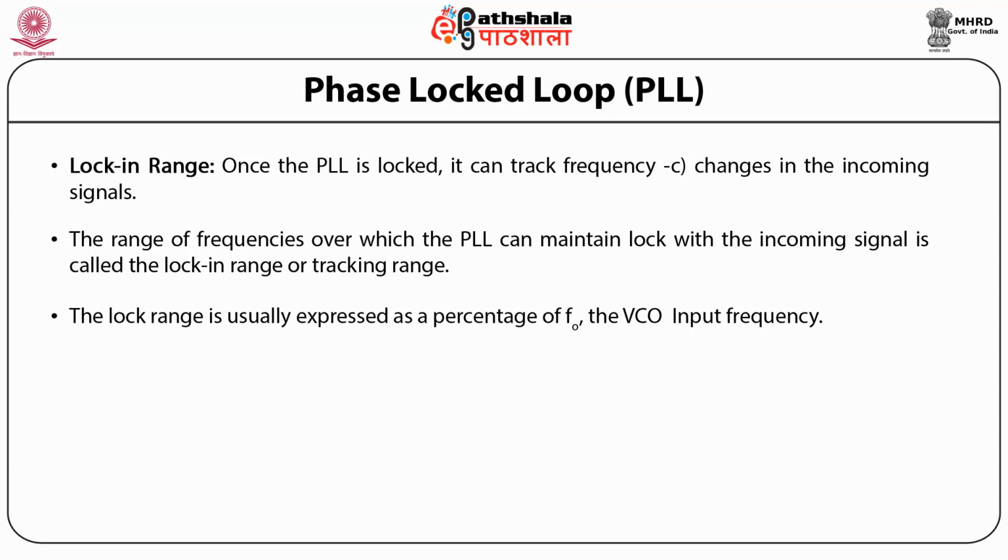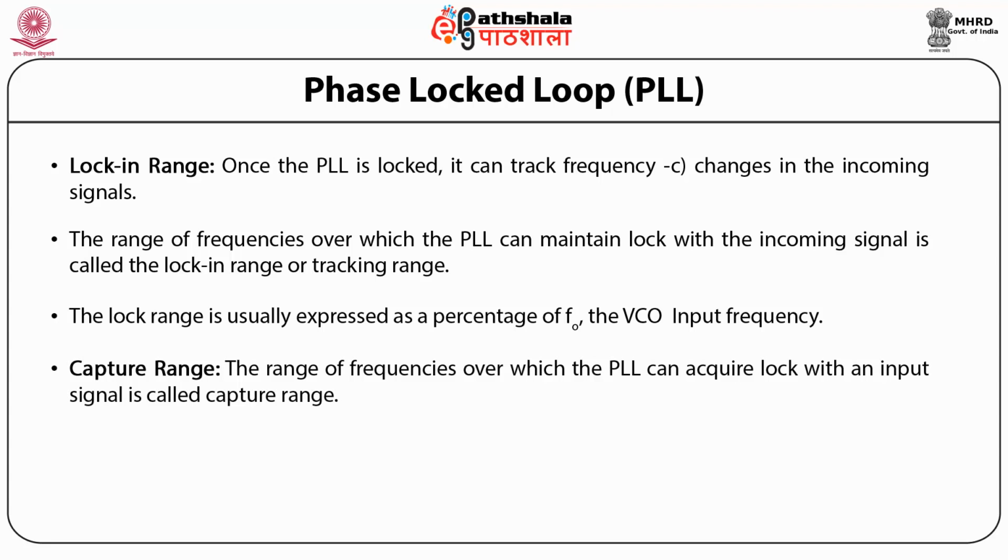Let us now discuss the capture range. The range of frequencies over which the PLL can acquire a lock with an input signal is called the capture range. This parameter is also expressed as a percentage of F0.